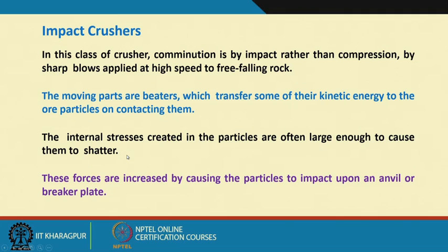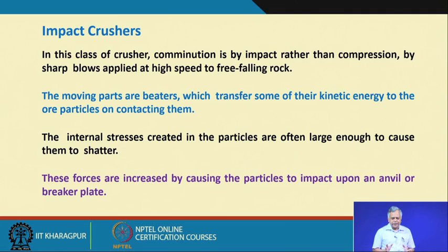It is similar to having a mechanical device throwing the material and hitting it against a very hard surface, like a wall made of, say, steel. The higher the velocity, the finer will be the breakage. So, you have to control the velocity to get a proper size distribution of your discharge product.